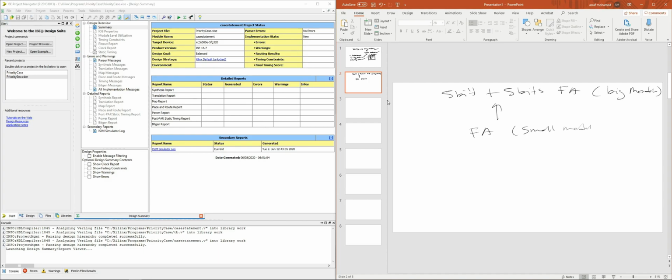Then inside this full adder, you're going to have a half adder, another small module. So whenever you want a 5-bit plus 5-bit adder, you're going to have several full adders, right? You can call as many times as you want, say 5 times: full adder 1, full adder 2, and so on. The same thing here: the full adder is going to consist of several half adders. You can call that half adder module several times as well. Now we're going to look in detail at how to achieve this example.